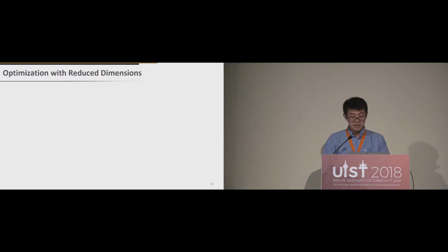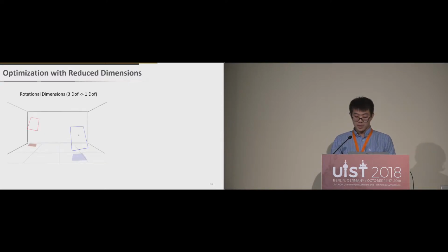Our unknown transformation has 6DoF, namely three translational and three rotational. However, with a closer look at the SLAM system, we can reduce the rotational degrees of freedom down to 1. Modern SLAM implementations usually involve a built-in IMU, the inertial measurement unit. Then the coordinate system of the SLAM map is actually aligned with gravity. With such an observation, we only need to consider the rotation angle theta about the y-axis.